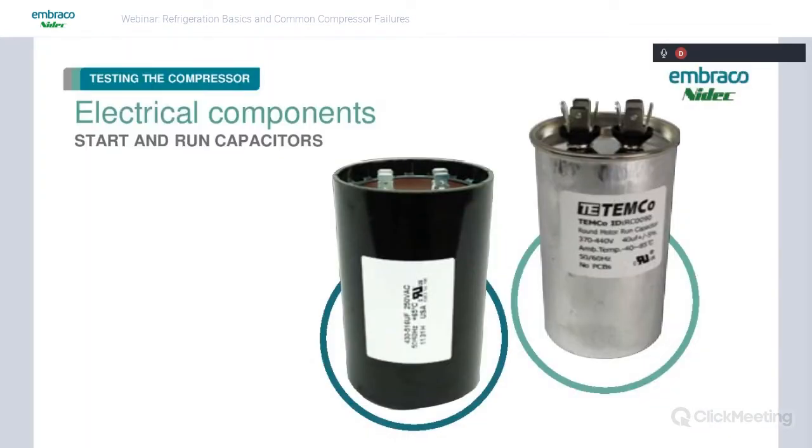Then we have two types of capacitors. We have start and run capacitors. Basically, the start capacitor is not designed to be held in the system, but just for a split second on startup. If you get a sticking relay, you're going to burn up that start capacitor very quickly.